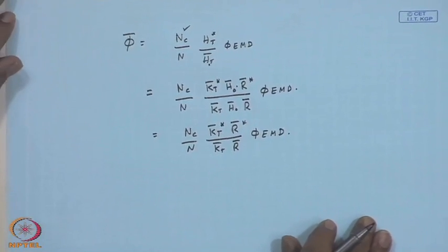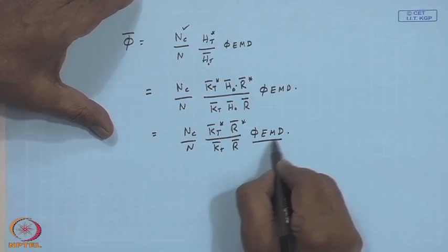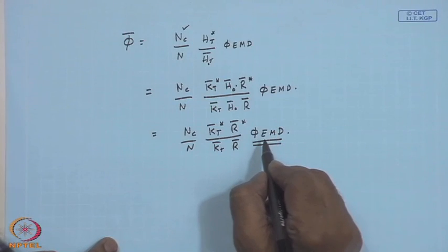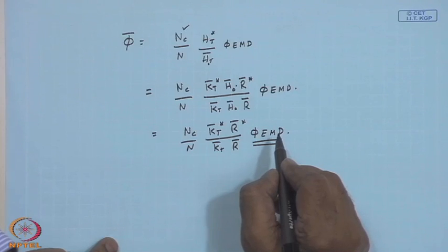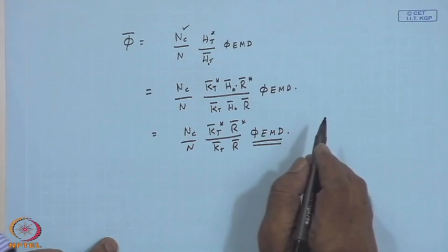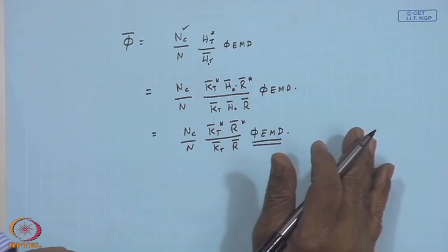So, I can calculate the monthly average daily utilizability if I can somehow calculate the single day's utilizability, that single day being the equivalent mean day, which we have defined as the day having a clearness index of the average of the days with the critical level lower than the noontime radiation, of NC number of days in the month.